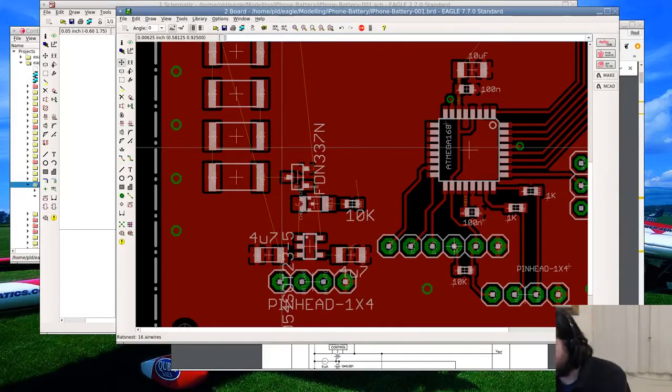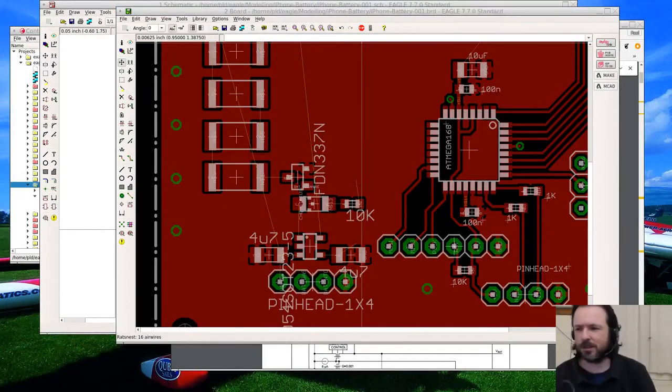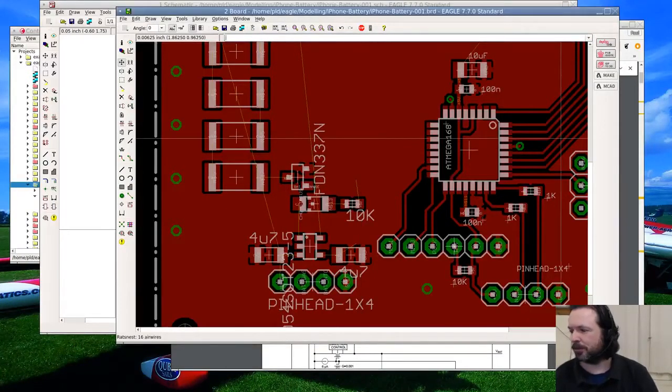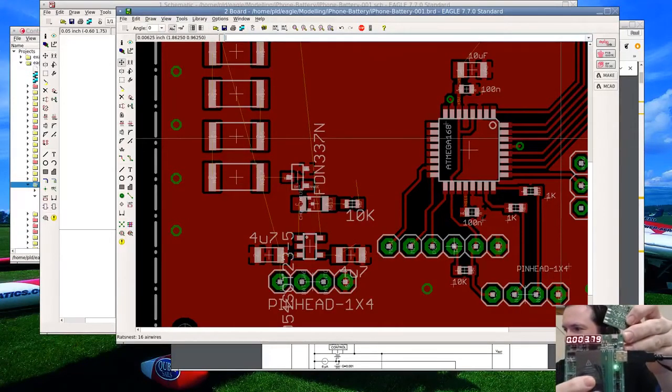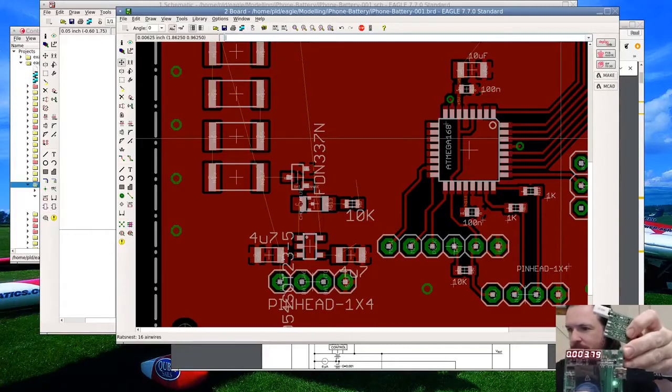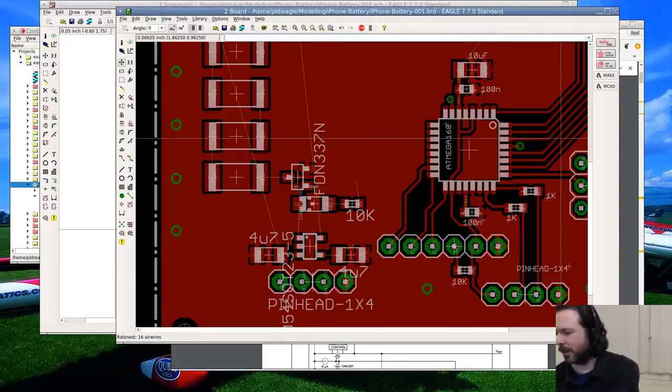Oh, by the way, there we go. I can't even see now where that is. There we go. We've stopped, and we're at 3.79, and that's the float voltage, so that's pretty much on the mark for what we want. So now I can put that battery aside safely, not worry about it ballooning or collapsing, and it should be good for about 6 months in storage.